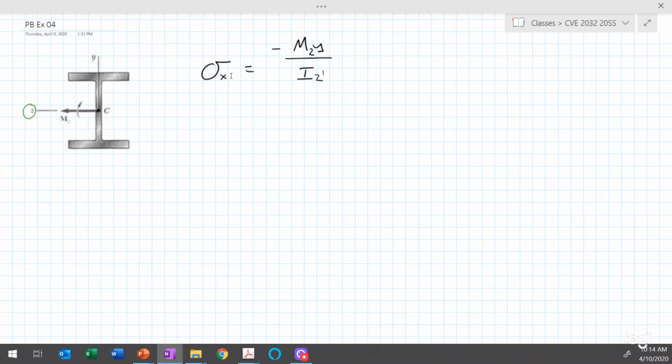All right, so with that in mind, what we want to do is figure out what the maximum stress is. It's going to be the maximum stress in the x direction. So we're going to set that equal to M sub z, and in order to find the maximum stress in the cross section, we're going to be looking at the fibers in the cross section that are furthest away from the neutral axis. That means we're going to be looking at y max or y min, and then we divide by I sub z again. I should have crossed these up here. Too late now.